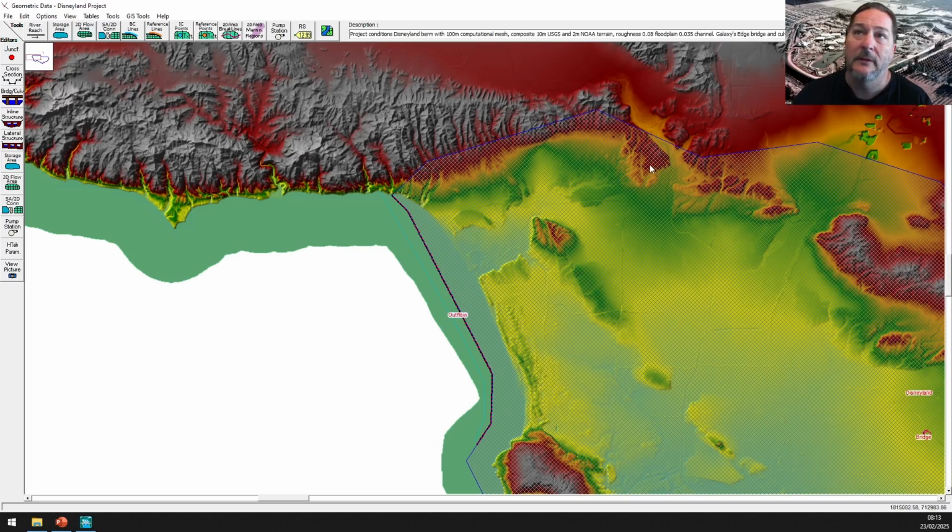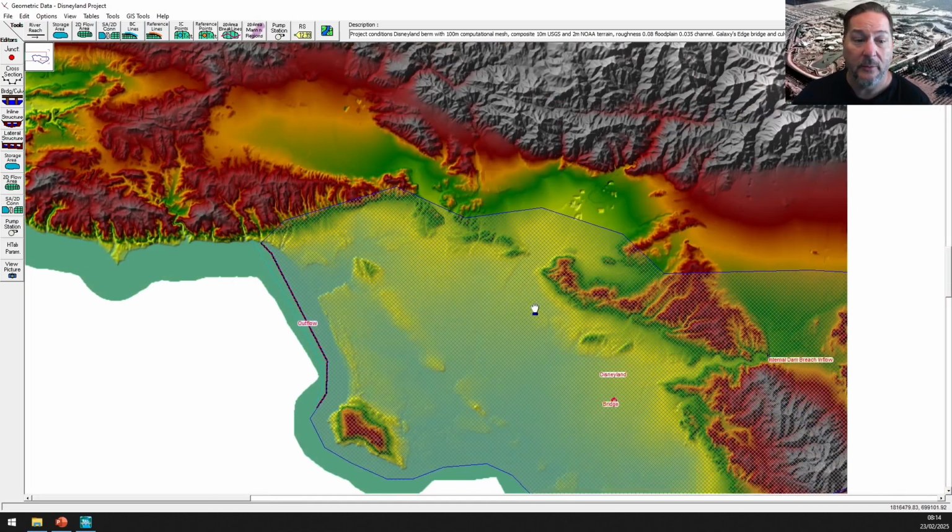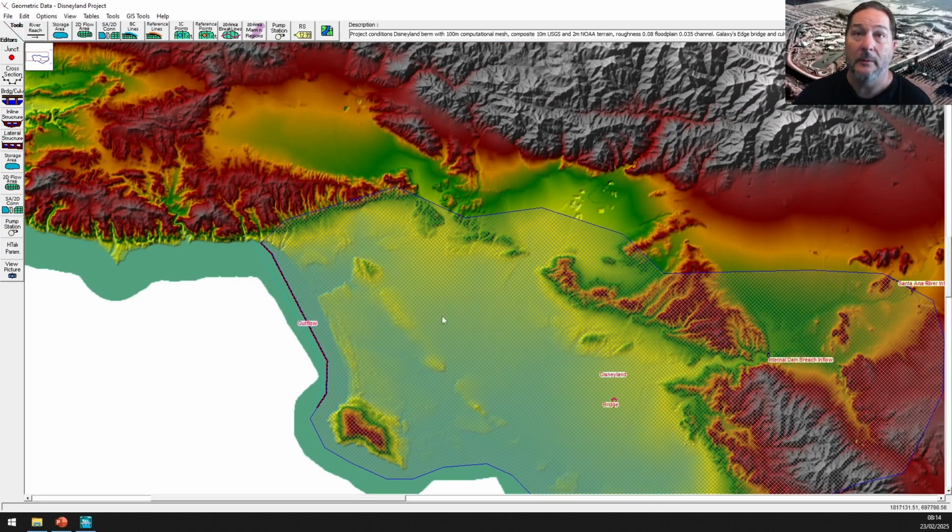Now, typically you would let flow out along an actual flow path, maybe this river here, and so you could measure that energy gradient. If that's just a single channel, that might be easy enough to assign. If you're just doing an average over the whole thing, then you'd probably want to test some sensitivities, try a couple of different gradients, and just see how far that propagates out. In our case, we're just doing it to avoid some glass walling here, so that slope might not be all that crucial.